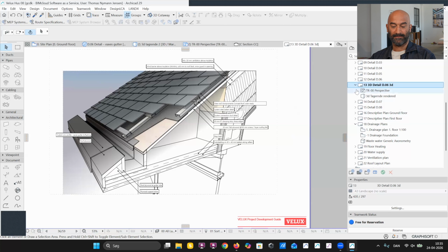The third layer would be a gradient, yes, hiding the render with white from the bottom right, and transparent in the other end, so it wipes out everything with a white color that fades into invisibility, so you'll see what's actually underneath that fill, and that will be the 3D render. So you still have to be a little bit creative to do details like this. Yeah, but it looks nice in the end, right? Exactly.